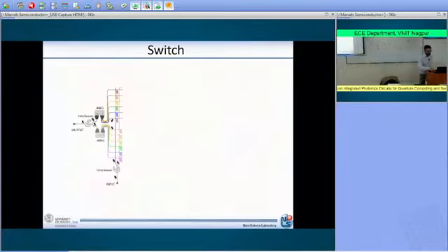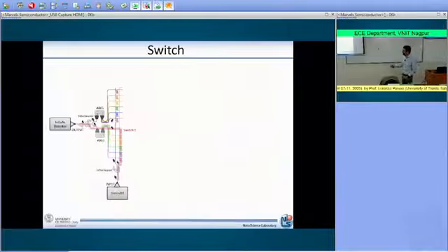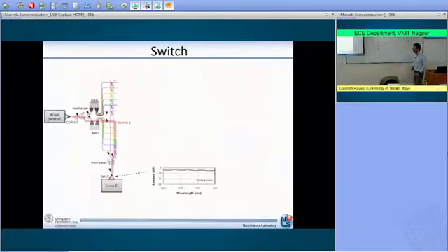So you start. You connect your laser to the input, you tune the wavelength, and you try to address the switching of this color to the output. And then you start to do the measurements. The first measurement is the grating coupler. You measure the amount of light that is transmitted into the photonic integrated circuit. What you see here is the measurement of the grating loss over the wavelength region that you are interested in. You see that the grating losses are quite flat.